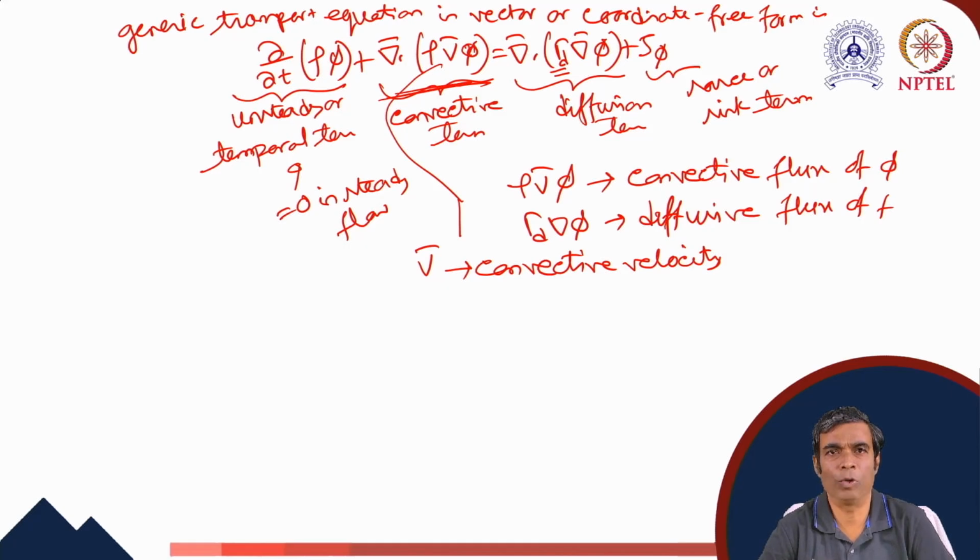So whatever the fluid flow phenomenon is happening, whatever terms are present, these terms will belong to one of these four terms. No more terms are possible other than these basic four terms, and this is the basic or generic equation. From this equation we can derive the mass conservation equation, the momentum conservation equation, or the energy conservation equation. So this is the generic transport equation.